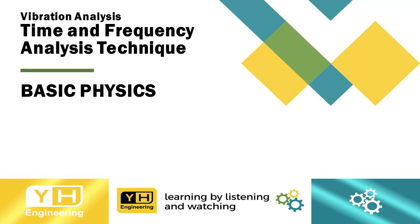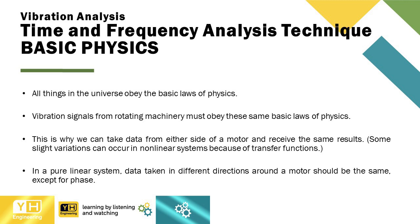Vibration analysis. Time and frequency analysis technique. Basic physics. All things in the universe obey the basic laws of physics. Vibration signals from rotating machinery must obey these same basic laws of physics. This is why we can take data from either side of a motor and receive the same results. Some slight variations can occur in nonlinear systems because of transfer functions. In a pure linear system, data taken in different directions around a motor should be the same, except for phase.